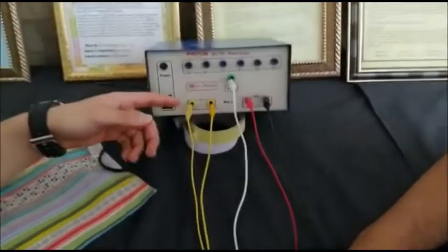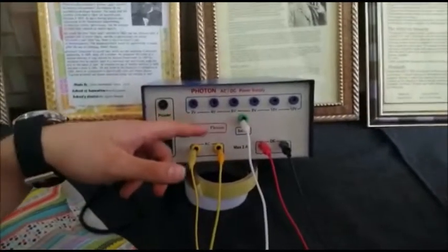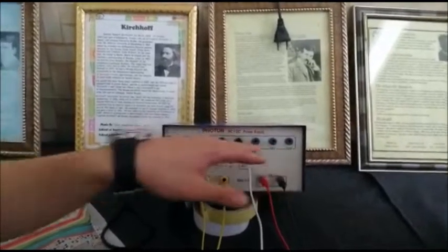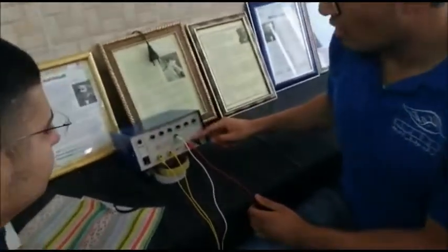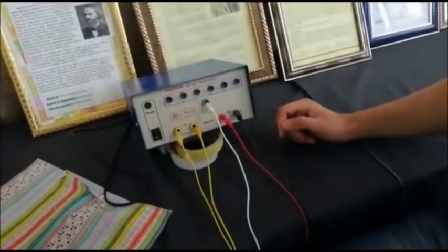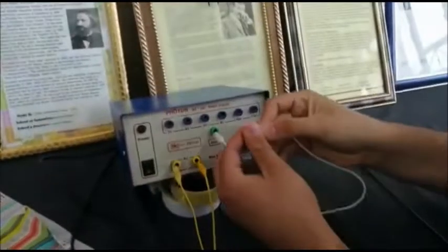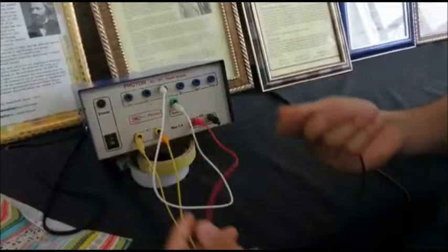We are talking about the power supply. As we saw, it's an instrument that has many current choices, as we can use it for AC current or DC current. Also we can choose any voltage that we need, starting from 2 volts ending in 12 volts, increasing 2 volts every time. For DC we have a positive terminal here and a negative terminal here. By working with the AC/DC power supply, we select what we need from voltage, such as 6, then open the circuit, connect that with positive, and connect that with negative.